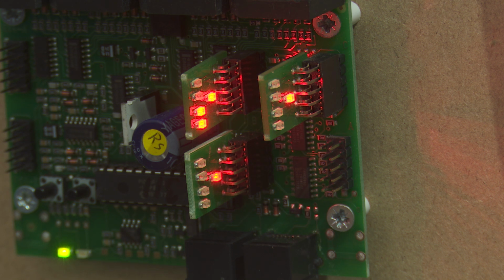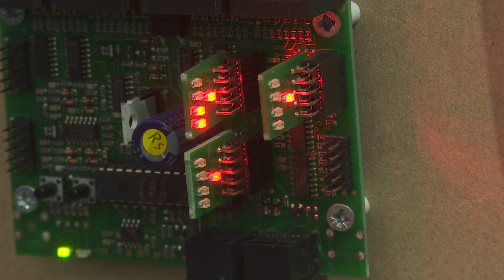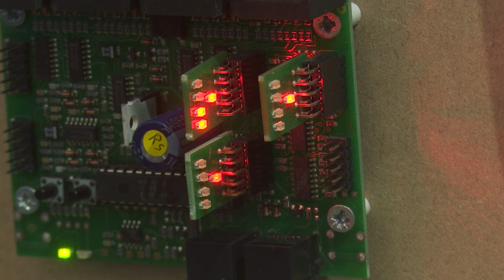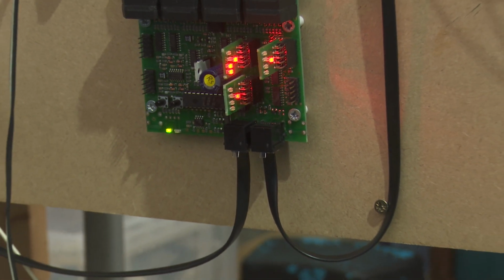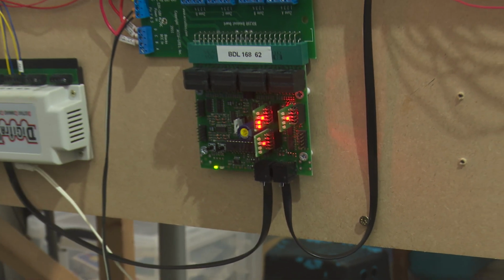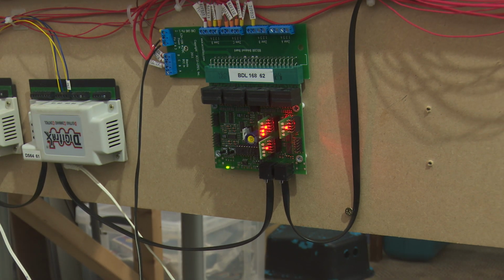The signal comes into this board, and it goes out on the LocoNet cables, which you can see looped in and out underneath, and then goes back to the command station, into the PR3 and back to the computer. So you've got the occupancy information going back to the computer, and that's really the guts of how it works.